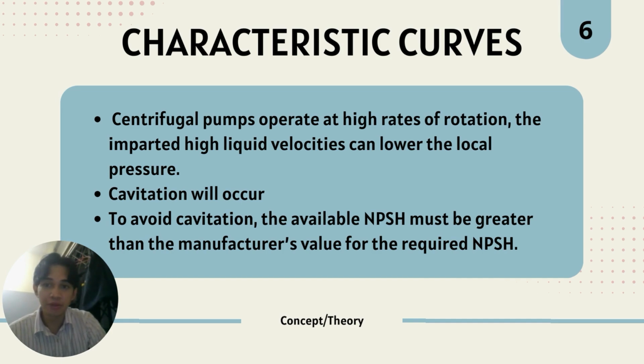The tendency for cavitation is measured by a quantity particular to each pump and available from the manufacturer, called the required NPSH, which is net positive suction head, defined as the difference between the liquid pressure at the pump inlet and the vapor pressure of the liquid, expressed as a head.